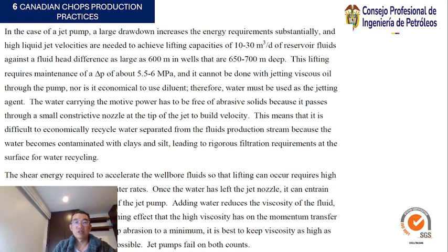The water carrying the motive power has to be free of abrasive solids because it passes through a small constrictive nozzle at the tip of the jet to build velocity.